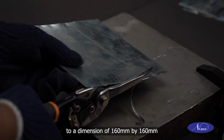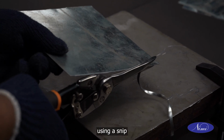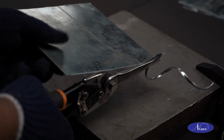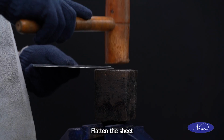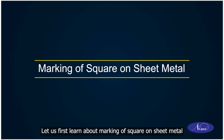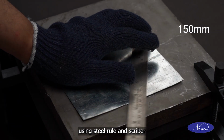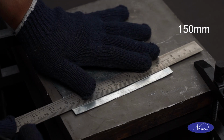Cut the sheet metal to a dimension of 160 mm by 160 mm using a snip. Flatten the sheet metal on tin man's anvil using wooden mallet. Let us first learn about marking of square on sheet metal. Mark a square of 150 mm on the sheet metal using steel rule and scriber.